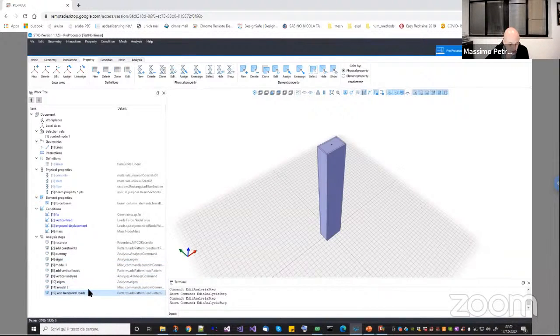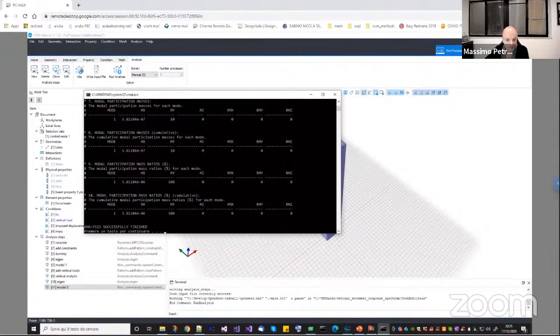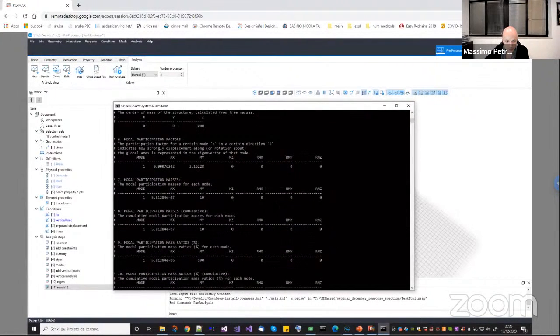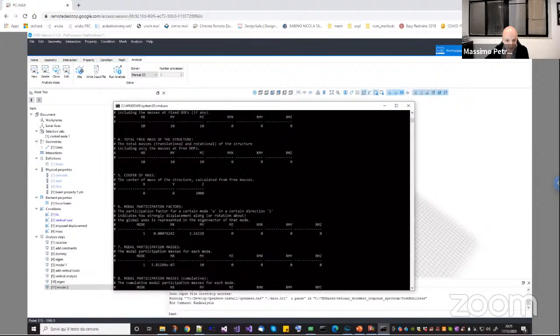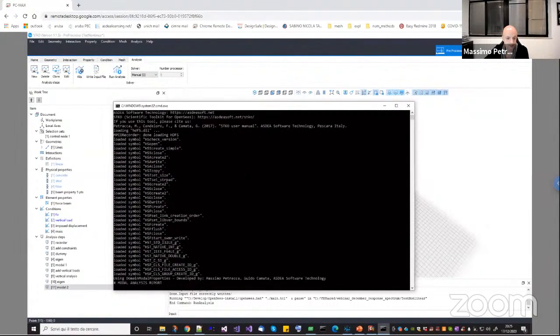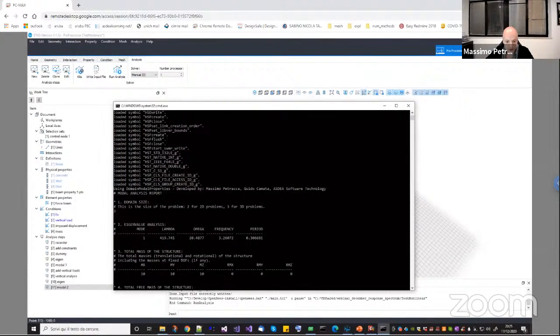Then here I was applying horizontal load and doing a horizontal analysis, but I just removed them because I don't need them, okay? So if I run this analysis, let's see what happens. Now, of course, here I don't have any rotational mass because there is no distance from the center of mass. Let's go at the very beginning. Okay, so first eigenmode, the period is 0.306, okay?